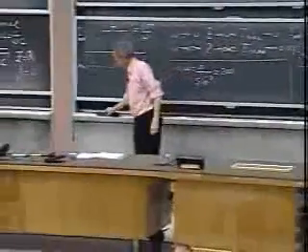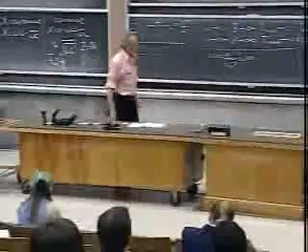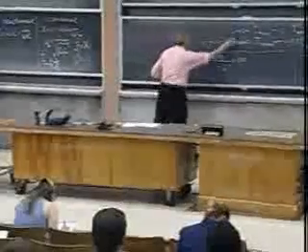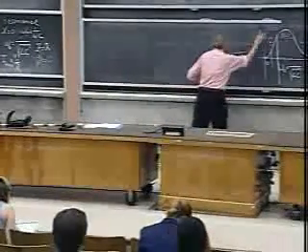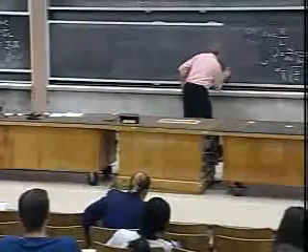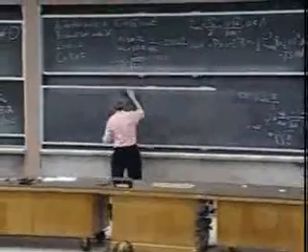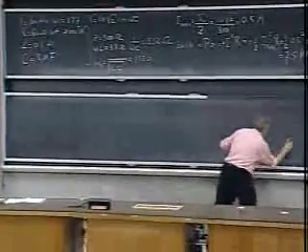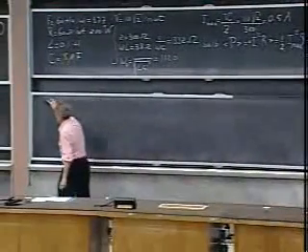Well, we know that our driving frequency is 377 radians per second. And so what we could do is change the C in the circuit, or change L in the circuit. If we increase C or we increase L, then the resonance frequency will shift down from 1120. Make L larger or make C larger, then obviously you shift your resonance frequency down. And my goal is to shift it down to 377 radians per second.